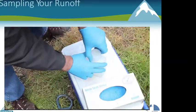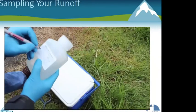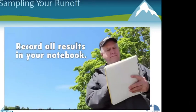Keep hands away from the bottle opening. Do not rinse or overfill sample bottles. Cap and label bottle with time and date, and place in cooler with ice. Record the result in your notebook.